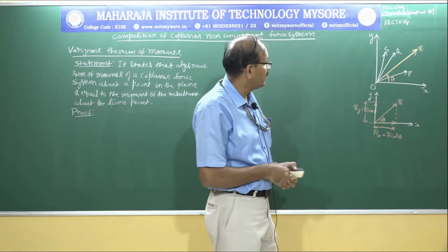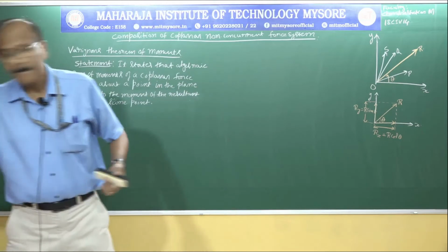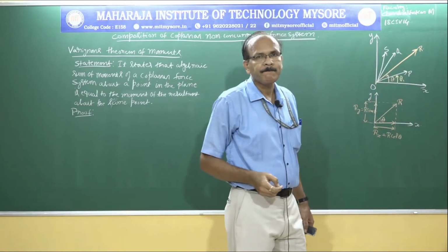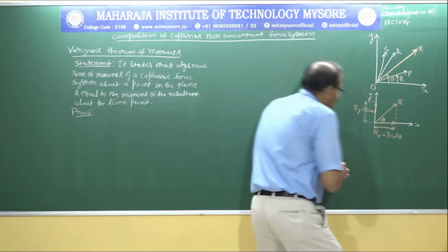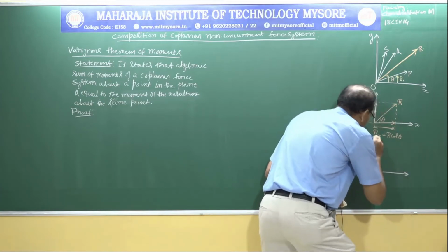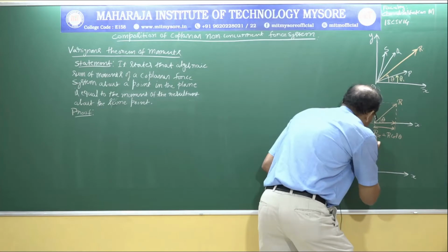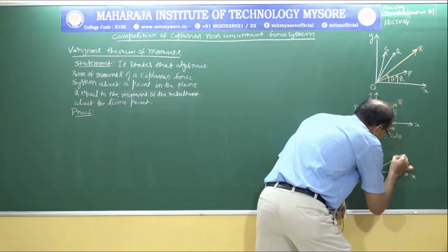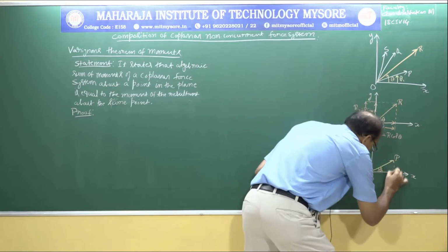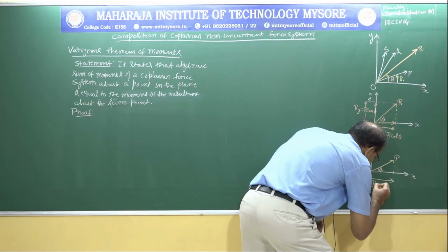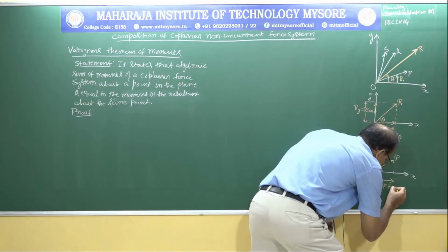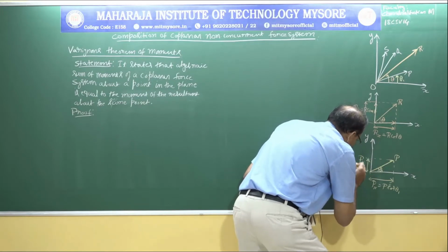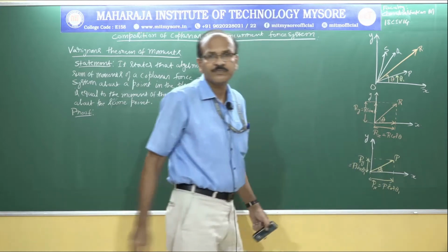Along the same line, if theta 1 is the angle made by the force P with respect to the horizontal, if I draw that separately, x, y, and this is P, this is theta 1, and the horizontal component is Px equal to P cos theta 1, similarly the vertical component is Py equal to P sin theta 1.